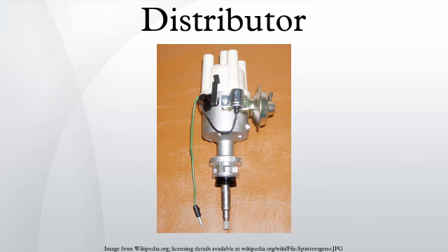Wasted spark. 4-stroke 2-cylinder engines can be built without a distributor, as in the Citroën 2CV of 1948 and BMW Boxer twin motorcycles. Both spark plugs of the Boxer twin are fired simultaneously, resulting in a wasted spark on the cylinder currently on its exhaust stroke.